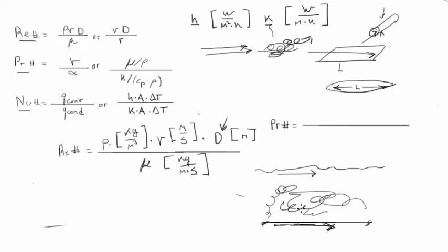It's a sticky fluid. Okay, so if you fill it up with water, how are these vectors going to look? Well, again, at the base, it's going to move at the same velocity as the treadmill, but it's going to lose velocity. It's not going to be able to diffuse its momentum as much. This vector should be shorter than that vector. And if it was just air, well, up here it's not going to be even affected at all. The air is just going to be still up here. Theoretically it will diffuse a little bit of momentum, but not a lot.